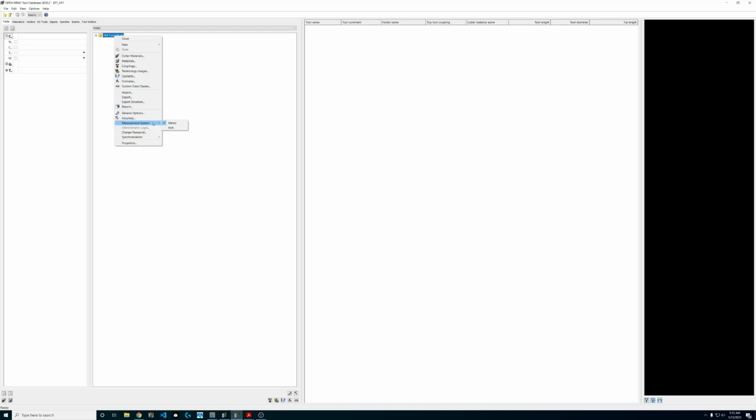Now, there's some other ramifications as well. While XML is supposed to be a neutral exchange format, if you've used other CAM software or if you tried to import XML files before, you may have found that it's not as neutral as you think. And good, bad, or otherwise, hyperMILL requires the XML file to be laid out in a certain way to really work correctly. So there's going to be some issues on the XML side and also the DXF.